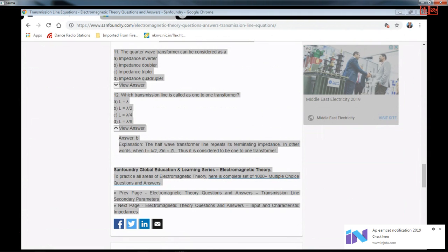Okay, so in terms of the cos and sine functions, the current on the transmission line can be represented in this manner: IL cos beta Z prime plus J VL by R naught sin beta Z prime. Please remember, this capital gamma, reflection coefficient, whatever we have been talking of, is a complex quantity, and its magnitude and phase will be changing along the transmission line in a general case, because on a transmission line the voltage will have different amplitudes and phases at different locations.